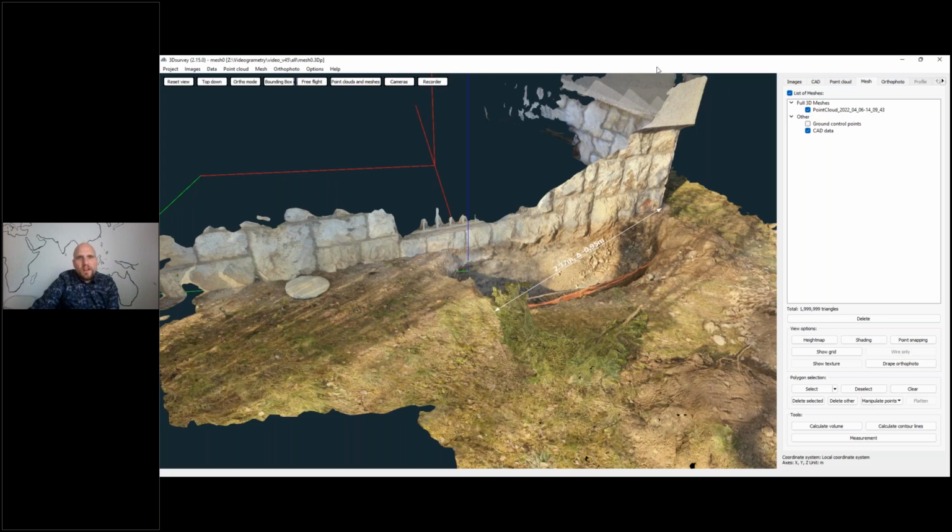Well, after you do a project in here, you can go to Project, Generate Report, Generate General Project Report. It will give you a report on the project. It will say what kind of accuracy we had on ground control points. But the report in this one is very drone photogrammetry oriented, but it will also make a report for videogrammetry.